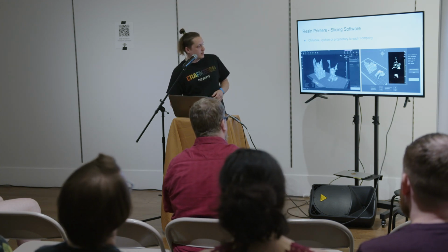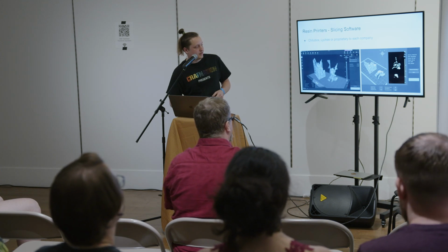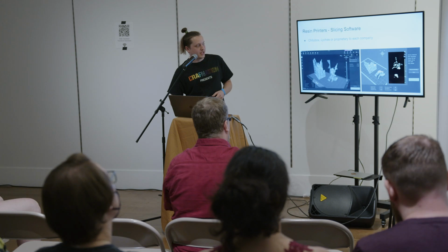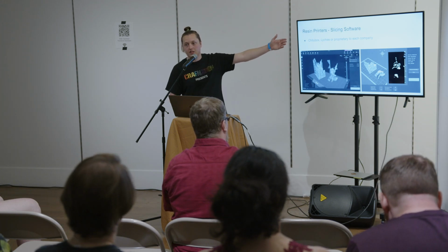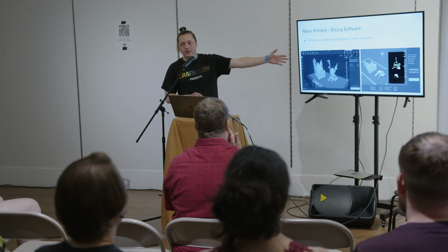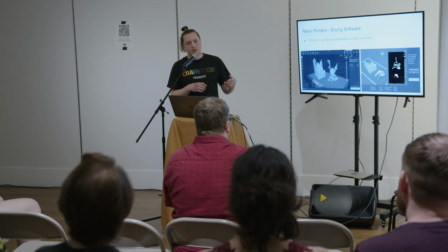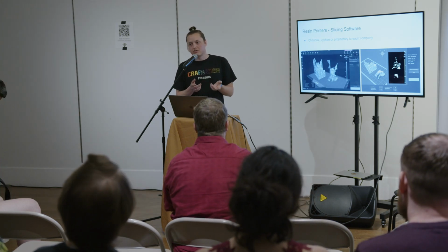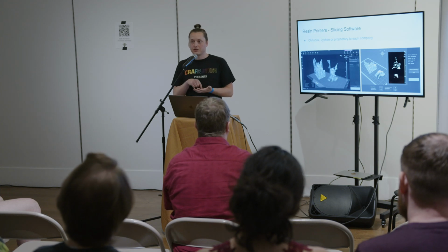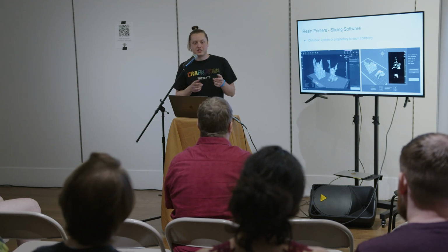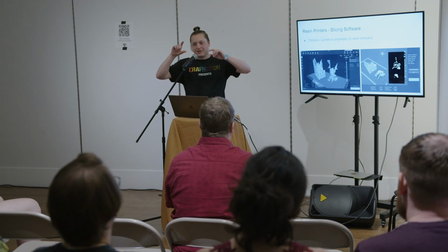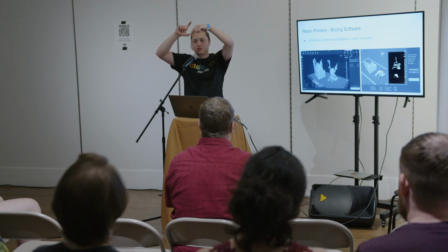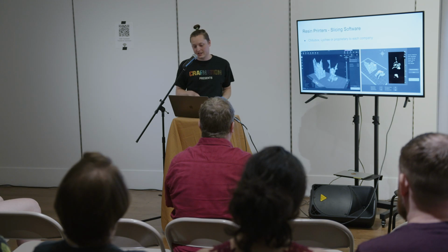And then again, we have a little slice preview. You can drag this little bar on the right up and down to navigate through what each layer of the print will look like. I pretty much only do this if I'm wanting to look for what are called islands, which is basically a spot that's going to get printed with no supports. Because if there's no support, it just sits on that vat film because it doesn't have anything to pull it off of the film each time the layers go up.